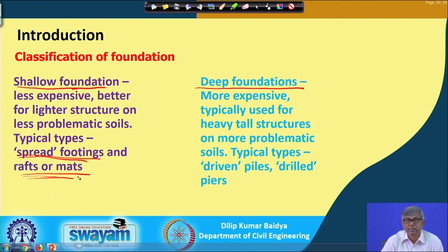And deep foundation, as I have already mentioned, is more expensive and typically used for heavy and tall structures, maybe also for heavy and tall structures on more problematic soil. Not only that: even when the soil is problematic, sometimes pile foundation or deep foundation is the solution. Typical types of deep foundation are driven piles, drilled piers, and sometimes caisson and well foundation also come under deep foundation.